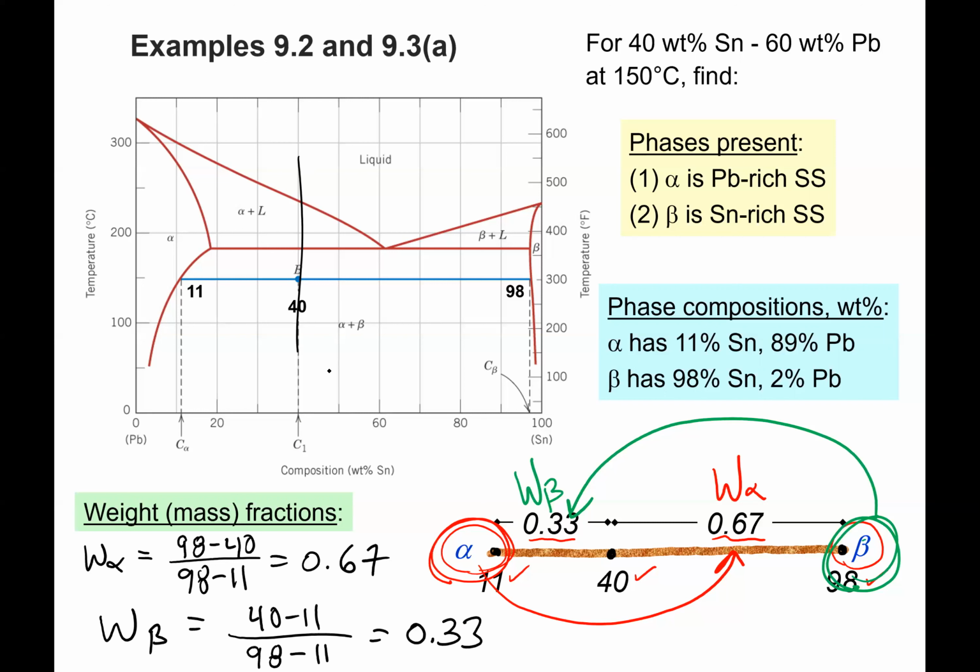And then they'll have another equation for the amount of beta if your composition happened to be over on the right side of the diagram, left and right relative to the eutectic point. So you got all these equations running around, and it's a complete mess, I think. All you have to do is this inverse lever rule. Trace out your tie line, pull it out of the problem, label it, and then pull off those fractional pieces. Always works. It doesn't matter where you are on the diagram.